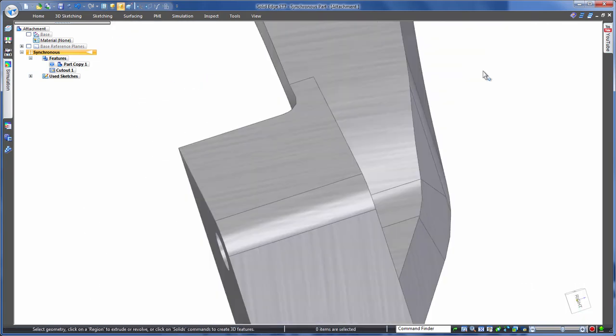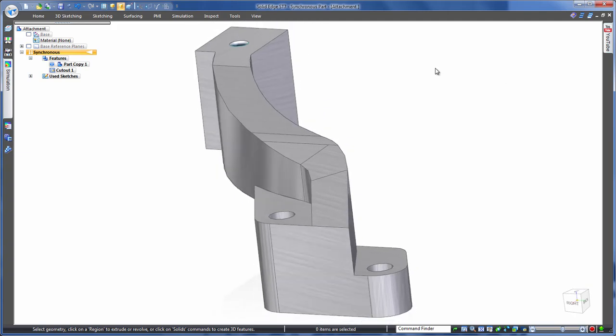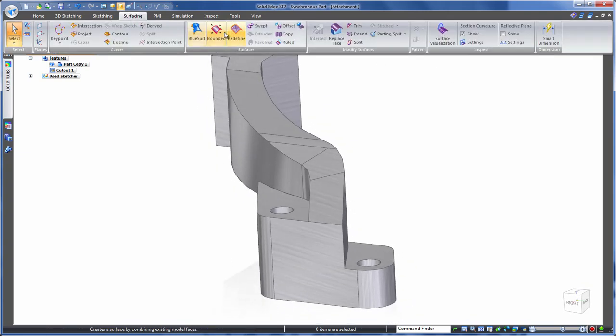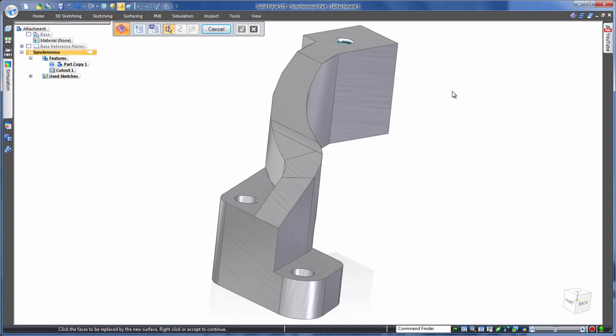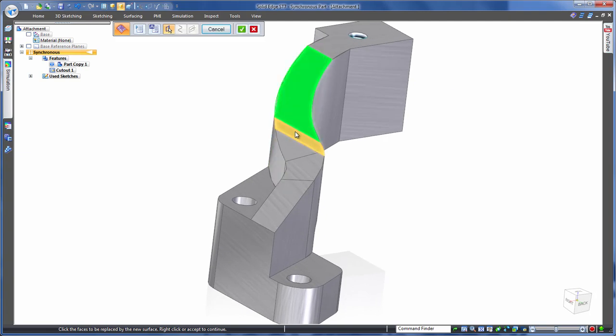The final preparation we'll do is in simplifying this top face. You can see that for some reason it has multiple patches, which may cause our simulation mesh to create unnecessary nodes and elements. Check this out. Solid Edge can take these 5 faces and turn them into one face instead.